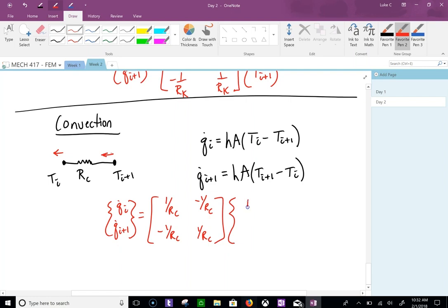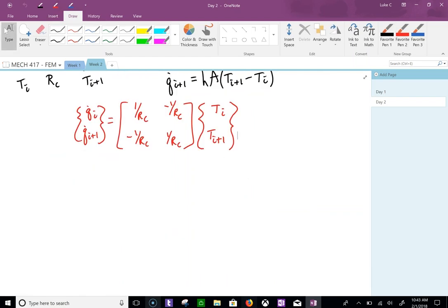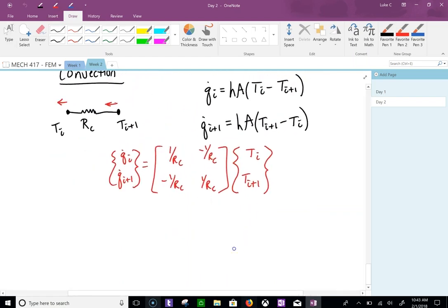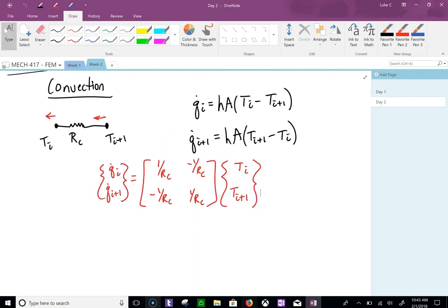Doing good on time. All right, so now we've identified the equations for each element. Okay? And do you have to do these again? No. You now know how to build your stiffness matrix if it's structures or solids.